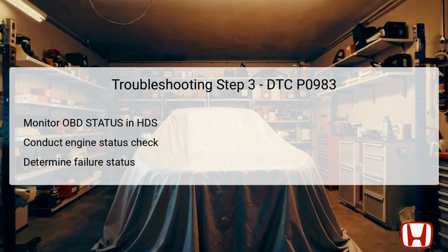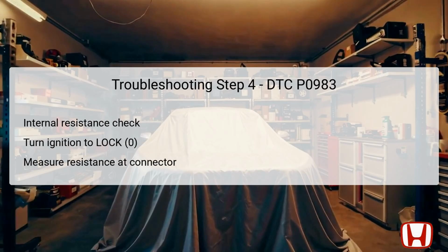If the status reads not completed, it suggests that further diagnostics or a test drive may be necessary. For the fourth step, an internal resistance check of shift solenoid valve D is required.